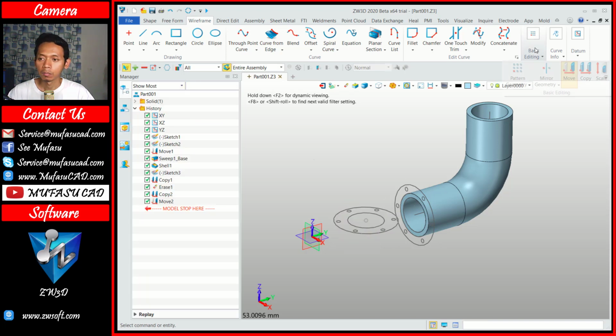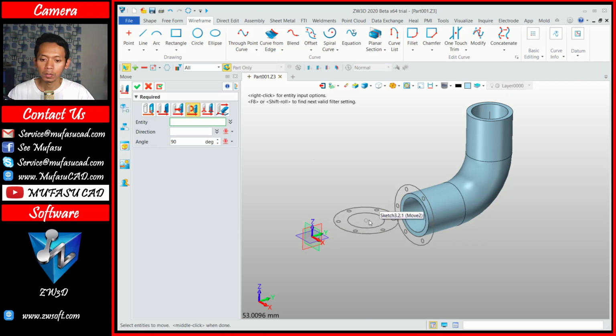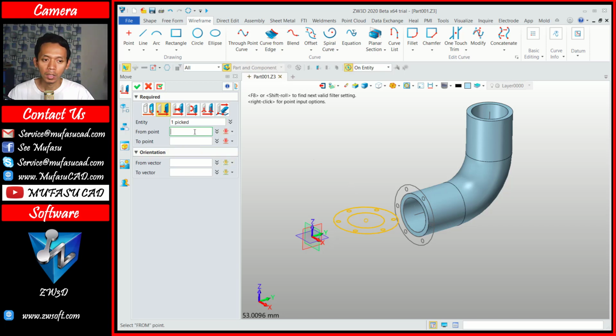Now we can use the move command again to move this object. Okay, I will use point to point. We select this point. Okay, you can click in here, click at this point, and then we can move to this point.